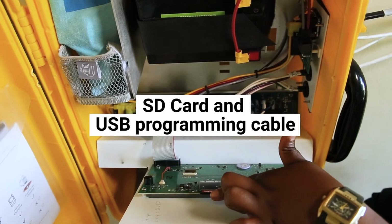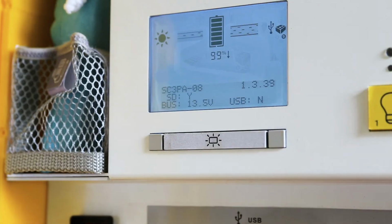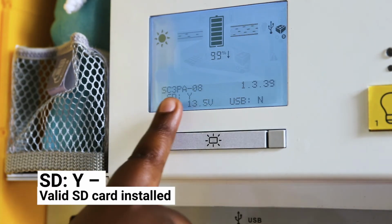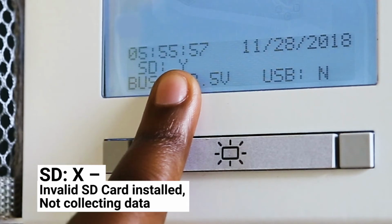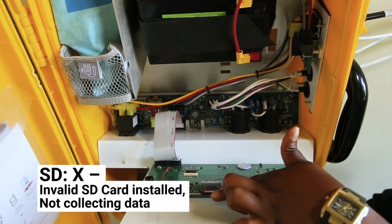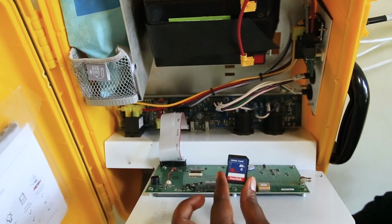SD card and USB programming cable. The final screen shows us whether a valid SD card is installed. SDY informs us there is an SD card installed and it is logging data. SDN tells us there is no SD card installed. And SDX is a card is installed, but it is not a valid card and it is not collecting data. In this case, replace the SD card with a functioning one.